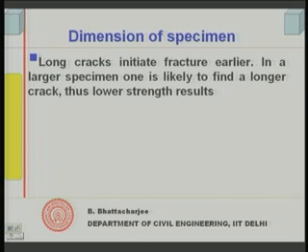It has been observed that the larger size cubes show lower strength, and it has been attributed to the possibility of finding a larger crack in the bigger size specimen. There is something called size effect in fracture mechanics, but this may not necessarily be the same, although it is similar, because in small size specimens it is not very easy to find the size effect, but some results have shown that a larger specimen is likely to show somewhat lesser strength than a smaller specimen.